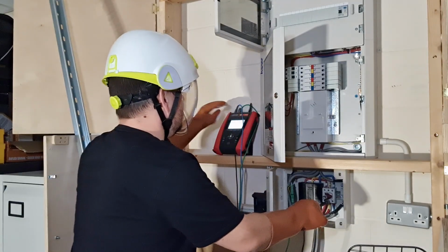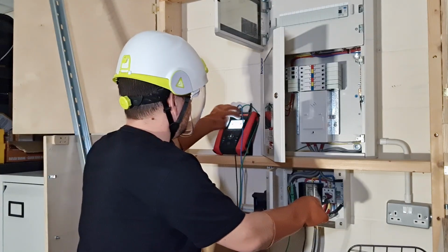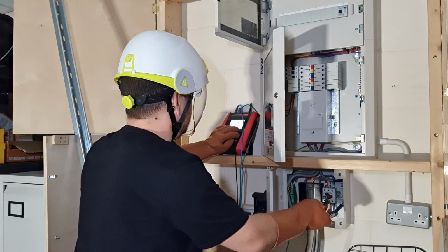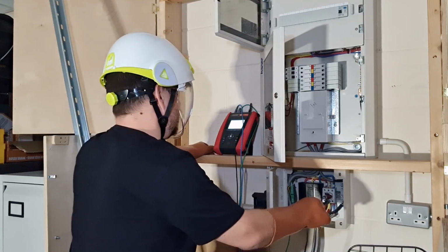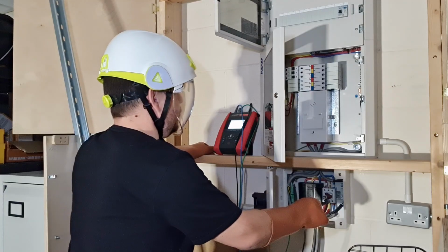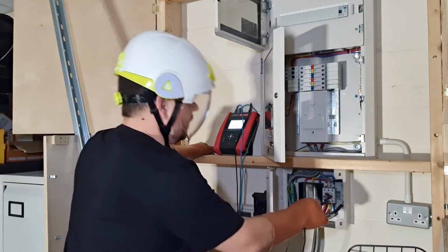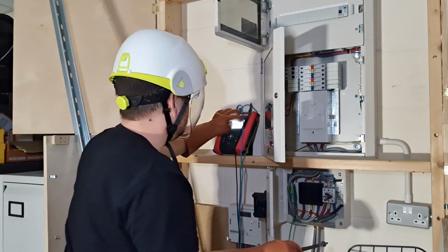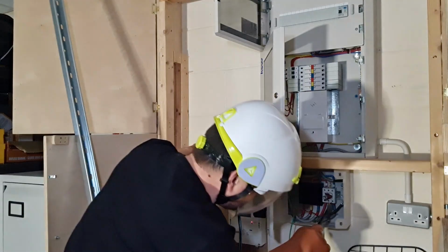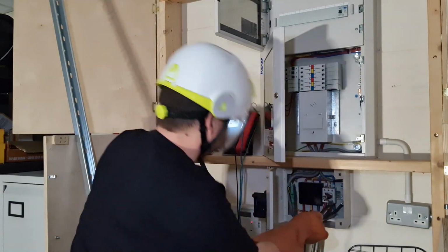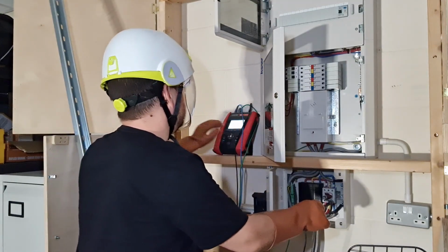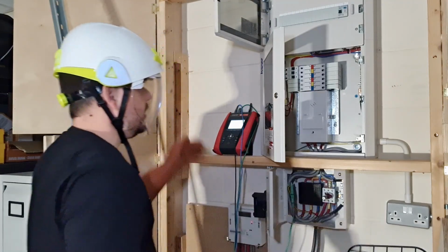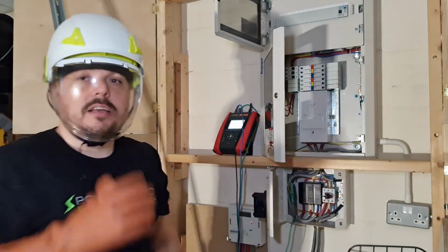Beauty of the TIS tester is it works with rubber gloves, so that's helpful. Again, same sort of voltage, 239. Hit test again, should be a similar figure. So we've got 0.08 and 2.18 kA on L2, and if I save that and go on to L3 is the final measurement, and we hit test, and 0.09 and 2 kA.